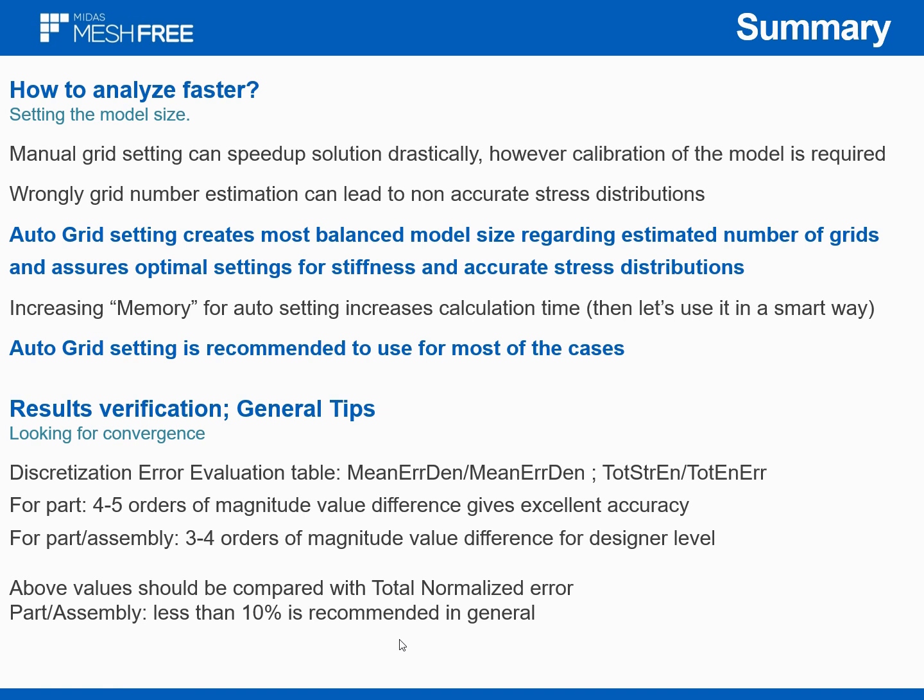So this also creates some kind of approach for dealing with assemblies with large number of the components, because you can exactly tell to the software at which part you are expecting to get accurate stress distribution in the same manner like for classic FEM approach. So we are doing convergence study. Increasing memory for auto setting also is not convenient all the time. It increases calculation time.